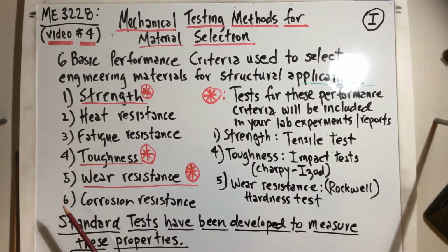toughness is the one we're going to talk about specifically, and probably not today in this first video, but next video I'm sure we'll talk about specifics of the toughness test involving, again, the impact tests, Charpy and Izod specifically. Wear resistance, again, is something very critical, especially for mechanical elements, all different types of motions, transferring of forces from one mechanical element to another usually involves mating pieces or parts, shafts, gears, belts, things like this. So wear resistance is very much a key ingredient.